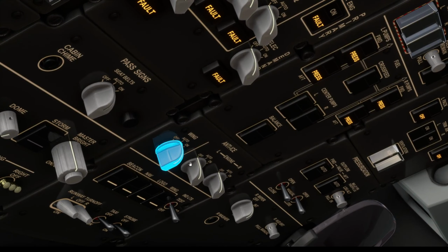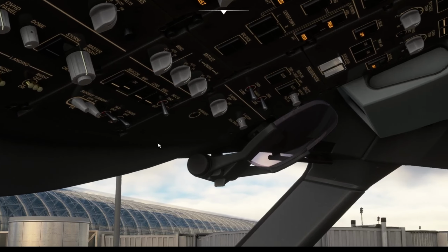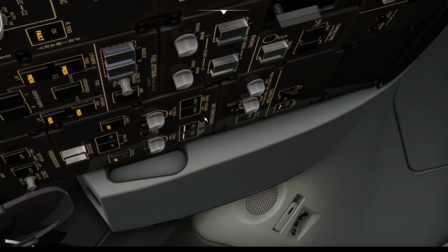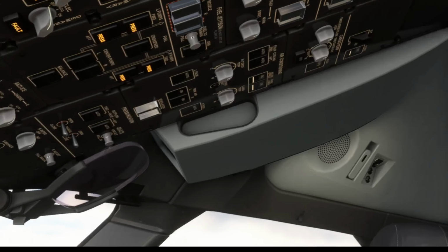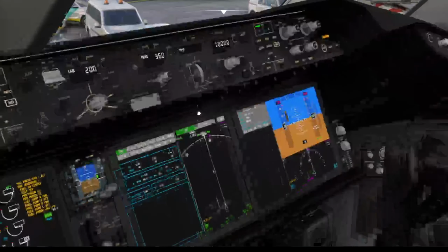We can put the anti-ice to auto, and then we put the nav light on. All the other lights basically remain off. Some companies like to turn on the logo lights, but I'm just gonna leave them off. It's daylight, so they see our tail anyway. Alright. Here, packs, they can go to auto. And this looks pretty much set as well.